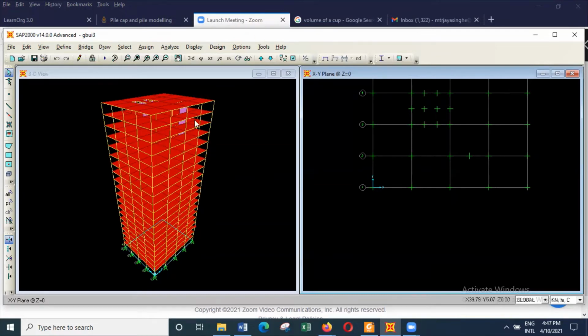So if I stop here and turn on the camera, here you'll see that because I'm deliberately going for 4 piles, the distance is 3,500 each on either side, 150. So altogether 4,300 millimeters. You get 3,000 and again 3,000 here, 500 here, 150 here. Likewise, you get the dimensions. So the size of the pile cap will be 4.3 meters by 4.3 meters.